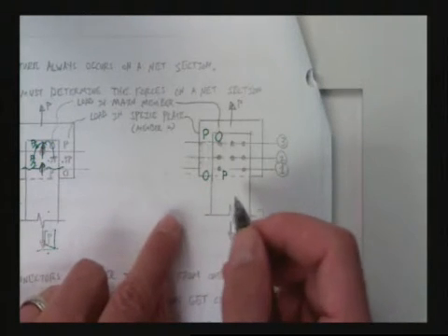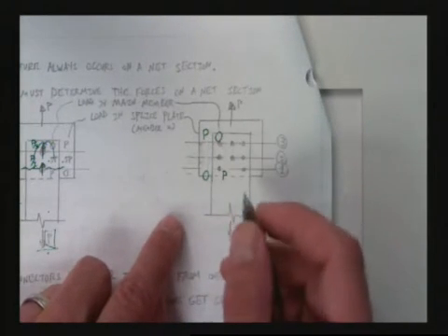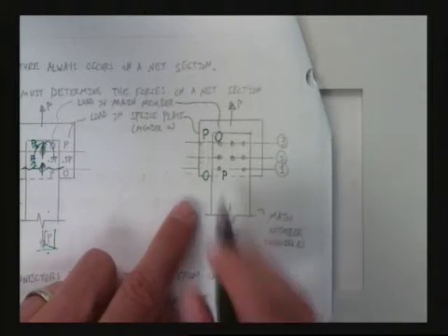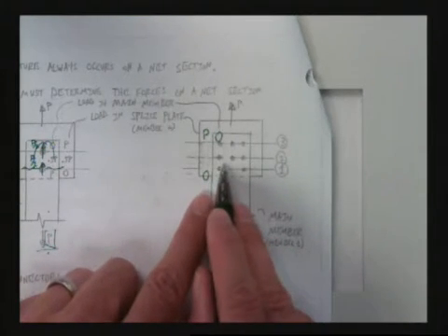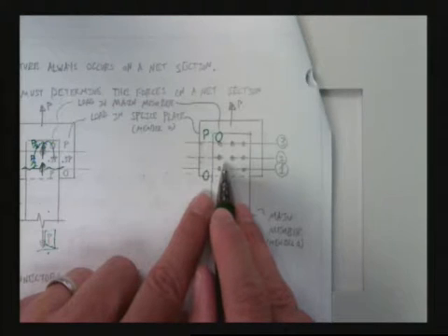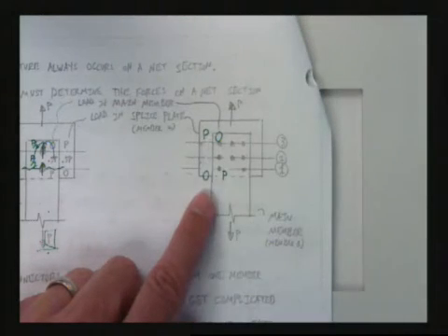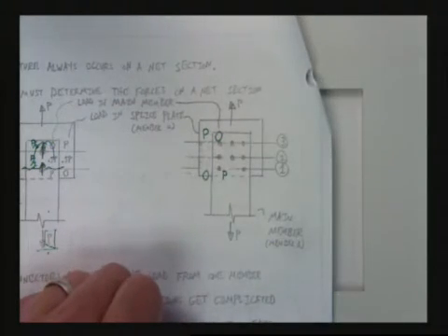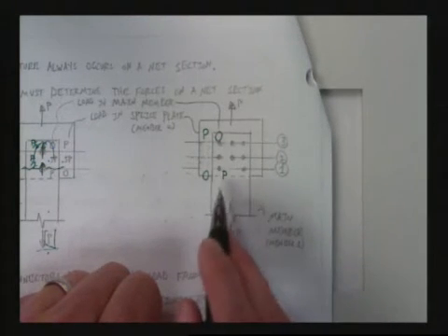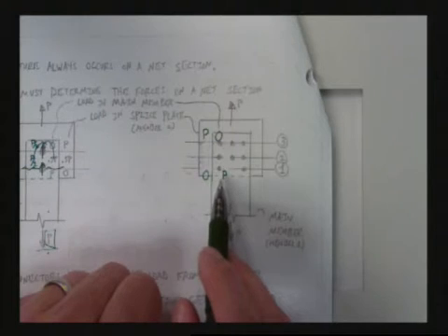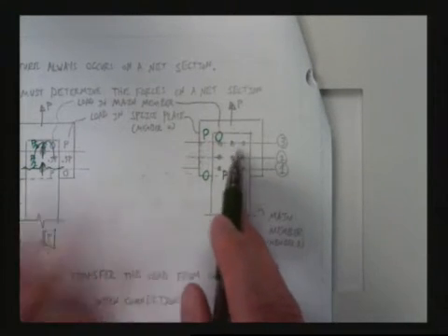Now let's do the ones in the middle. It's always good to get the easy ones out of the way, right? Okay. So what's the load going to be in this plate? 6/8 P. How'd you get that? Well, if they're all at their limit state, those 2 bolts would be making 1/8. Exactly right. There's 8 bolts.